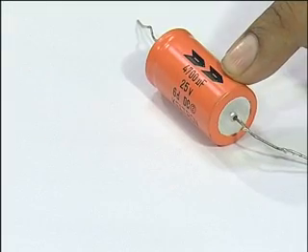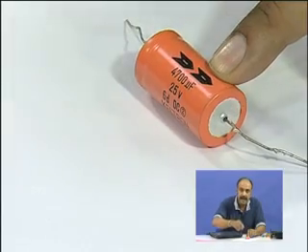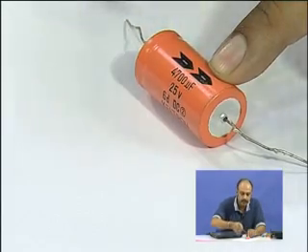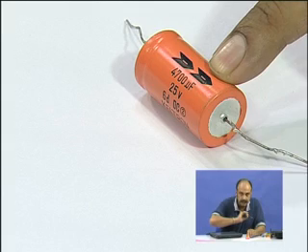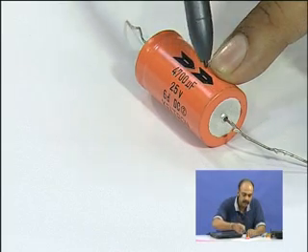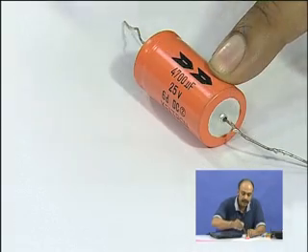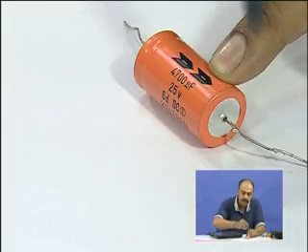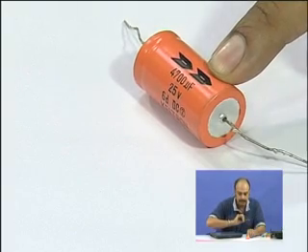With some marking here. Now, this capacitor has leads on this side. This is an axial lead capacitor. It is 4700 microfarad capacity value. You see the minus sign here with an arrow sign, which means this lead is negative, which means this lead should be more positive than this at every instant of time. So, this is a polarized capacitor.